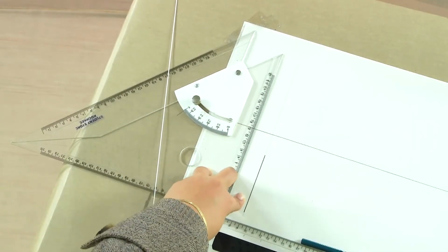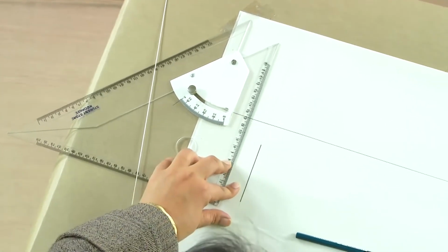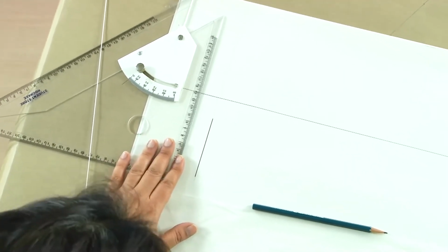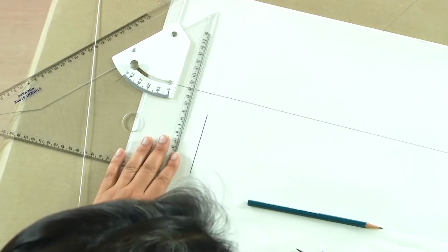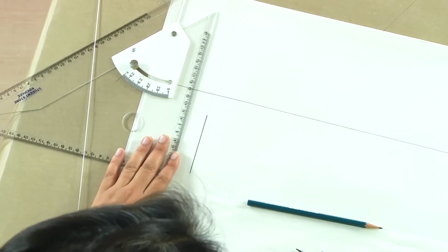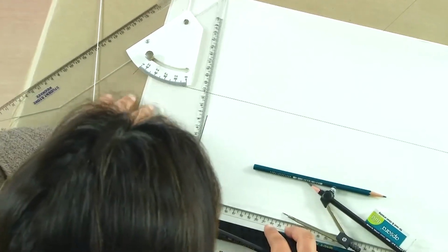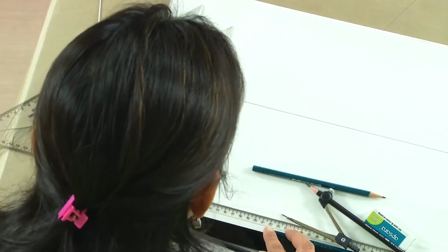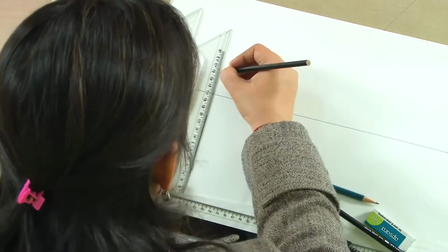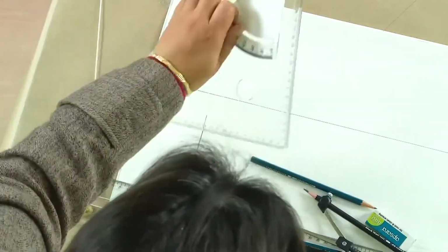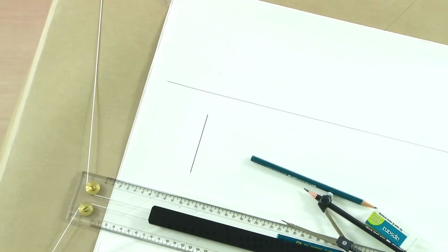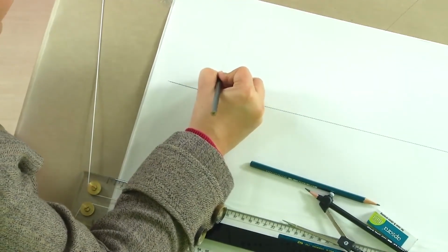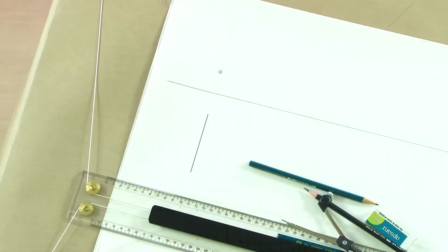This is the plan view of this line, which is represented by this condition here, and in the elevation we see a point, but where will we see it? It is at a distance of 30 mm to HP. So, we will measure a distance of 30 mm from XY, and this is one single point. So, what do we see here? We just see a point here, which is like this.